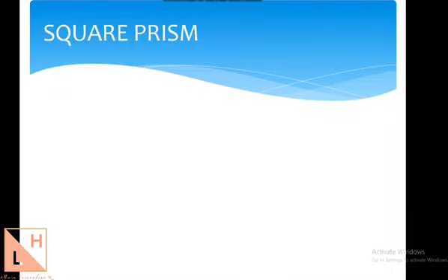See now, this is a square prism and we see that there are some dotted lines drawn here. Remember, these dotted lines are the ones which are hidden. Viewing it from this forward direction, you see that the square prism has the edges visible, and the edges which are dotted are edges which are hidden. If it is a continuous solid line, then it is a visible edge. If you just think of a square prism and hold it at this angle, the hidden edges will change depending on the orientation of that particular prism.